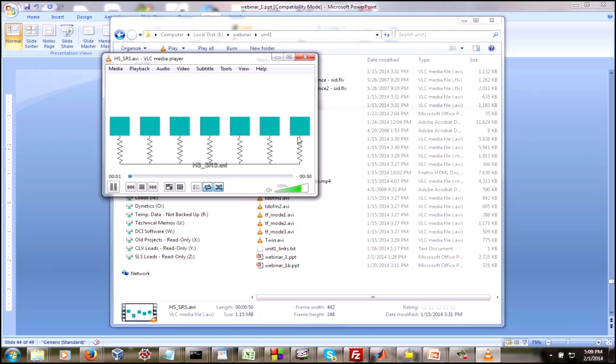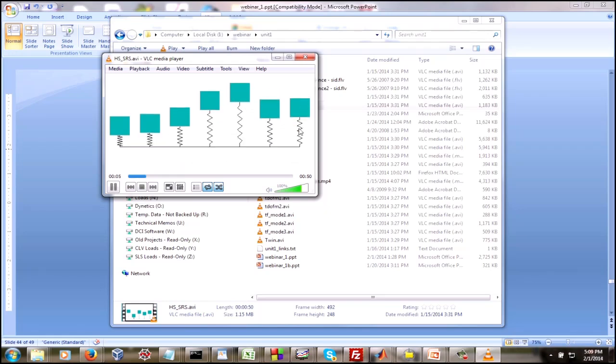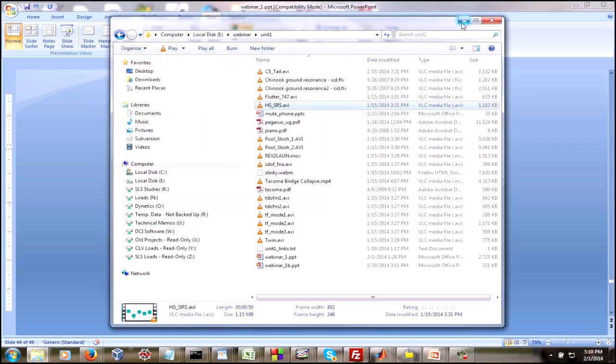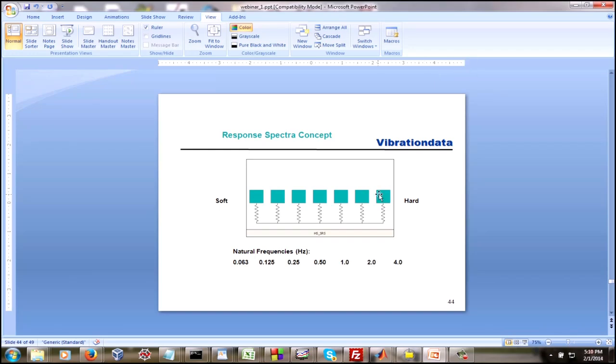We've already seen an example of where a stiff system is advisable, and that's the case if we're mounting a satellite payload into a Pegasus launch vehicle. We want the natural frequency of the payload's own cantilever mode to be 20 Hertz or higher per the payload user guide. So situations vary, but that's just a brief introduction into a shock response spectrum, and we'll also be covering vibration response spectrum in an upcoming unit.